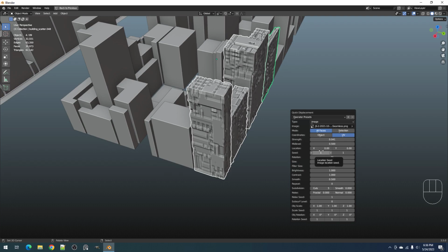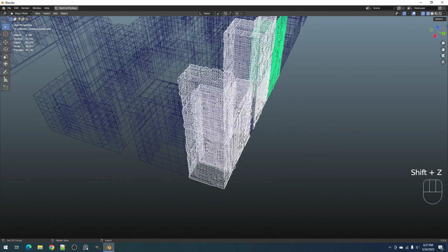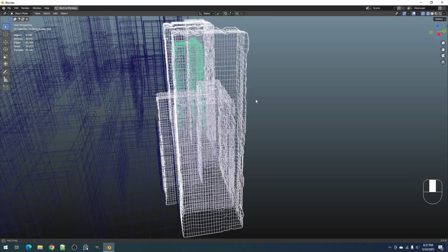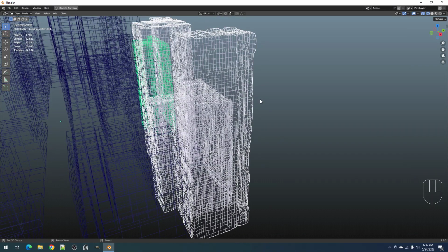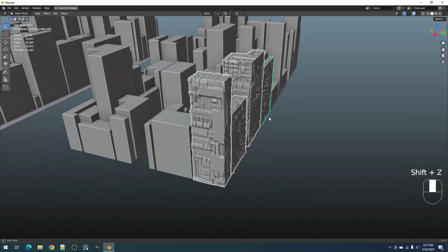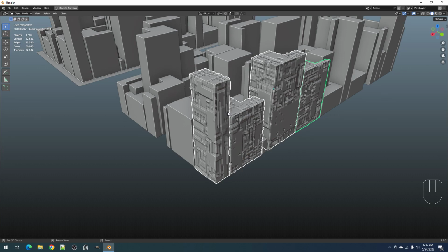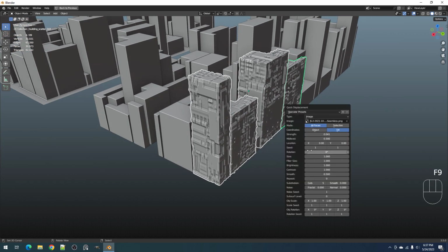You can reduce the faces using decimation, but if you use decimation on an ultra high res mesh, it will of course be very slow. So what we're aiming for here is not too high of a resolution, and still have the fidelity of the detail that we want.